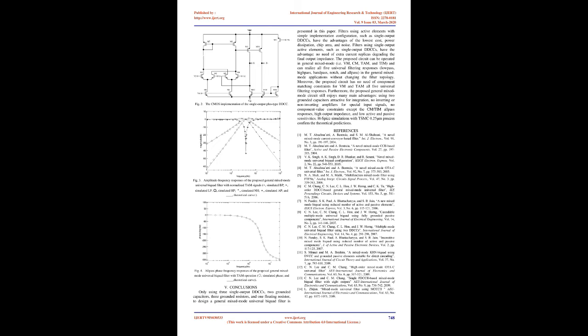Inspection of 1, 2, and 9 shows that, in all cases, the parameters ω0, ω0/Q, and Q are given by the following. From 10 and 11, the parameters ω0 and ω0/Q can be orthogonally adjustable by tuning the grounded resistor R2 for ω0/Q first and then resistor R1 for ω0 without disturbing parameter ω0/Q. However, 10 and 12 show that the parameters ω0 and Q are interactive.